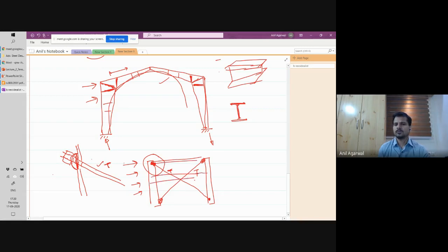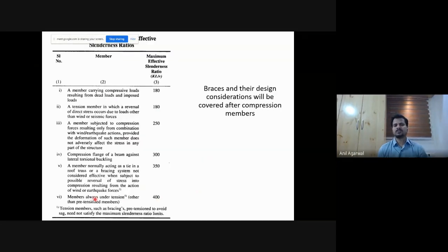So both of these will move, and this particular brace will undergo tension. And this other brace does not have to undergo compression, as it is going to either lose contact or it is already in so much tension that the tension will only reduce. It will not really go into compression. So for such members, you don't even have to satisfy any requirement of L by R. You will see that these are very thin, long rods, and they offer enough resistance.